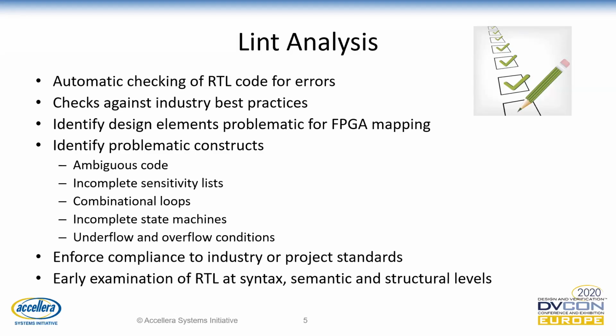Lint can also enforce RTL compliance to industry standards or even project-specific standards. So some of these standards could include, for example, DO-254, or even company design guidelines. Finally, the early examination of the RTL at syntax, semantic, and structural levels will reduce design costs by detecting problems early in the project flow.